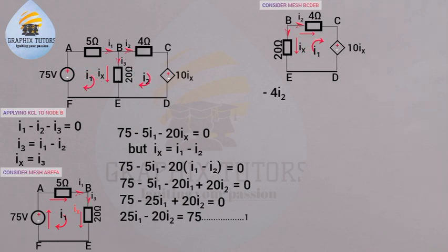Now, since we are moving from a positive potential to a negative potential, that is, from a high to a lower potential, I'll be having negative voltage also. So it will be minus 10ix. Is that taken? Plus, now we're not climbing up. Look at the direction. We're moving in this direction, but we're not opposing the direction of the current, right? And that will now give us positive.